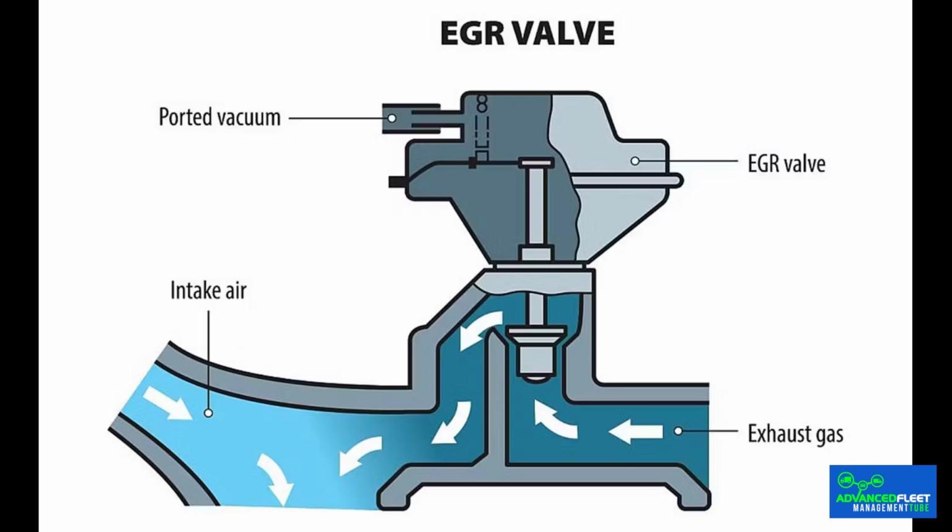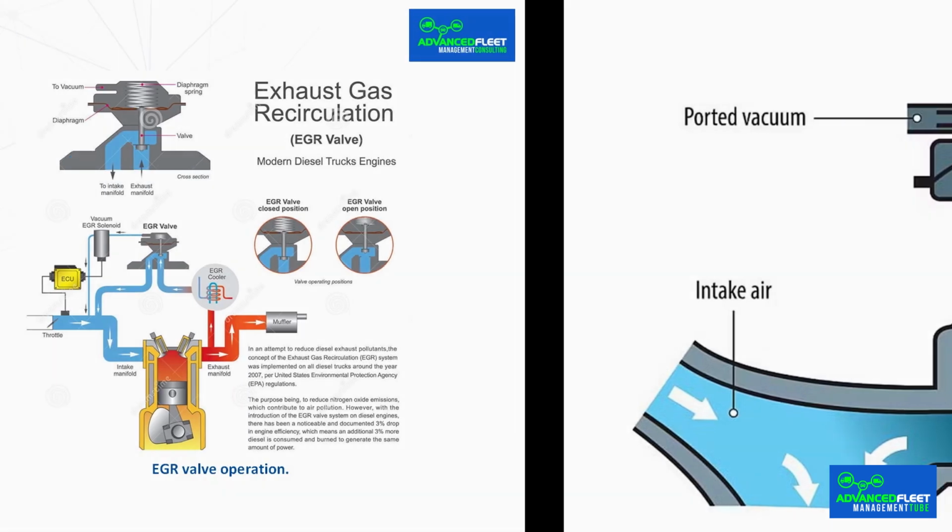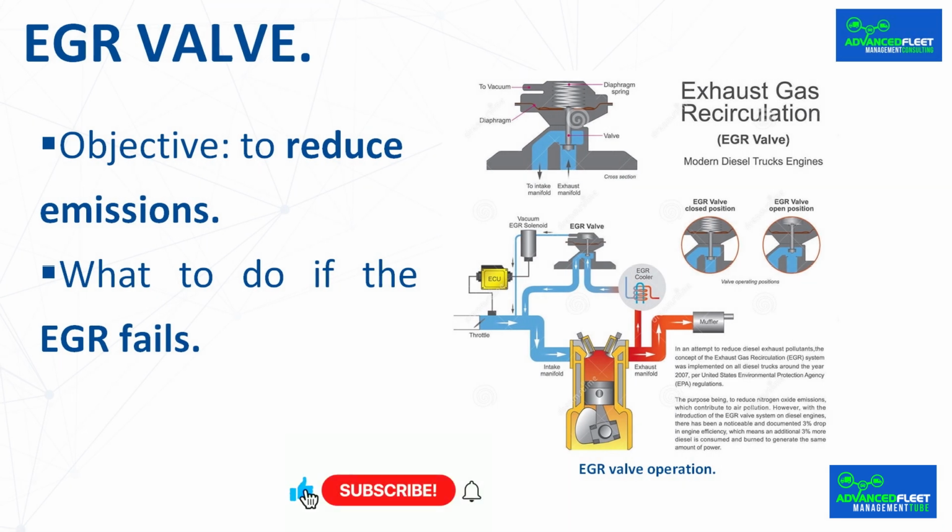That valve is the EGR. In addition to helping to reduce NOx emissions, EGR speeds up engine warm-up, especially in diesel engines, which need more time to warm up. Since the gases resulting from combustion are already hot, the mixture of clean air and these gases that enters the engine when the EGR is open allows the block to warm up faster than it would with clean air alone. It must be emphasized that this happens when the EGR valve is open, because sometimes it remains closed and the mixing of air from the intake and exhaust manifolds does not occur.